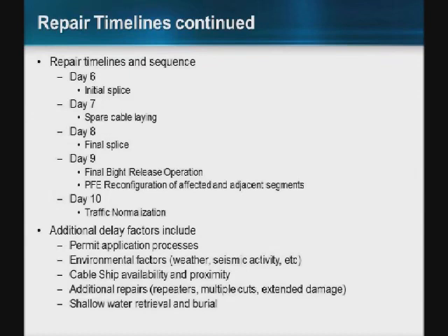So the permit application process, depending on the territorial waters that you're in to do the repair, could take anywhere from a couple days, a couple weeks, or even longer. Some environmental factors that come into play, typically weather, additional aftershocks from seismic activity, cable repair ship availability and proximity. So where is the cable ship docked? How far away is it from the actual fault? How long is it going to take for it to head to that fault location? And then shallow water retrieval and burial, additional equipment and time incorporated with actually burying the cable to protect it in shallow waters.